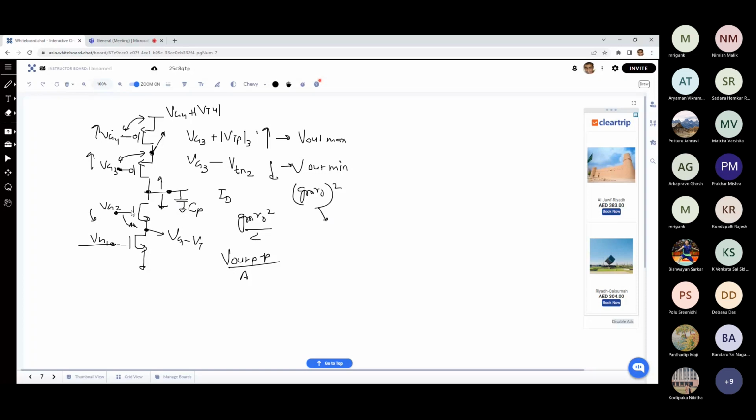So even if you say that output swing is somewhere close to, say, 500 millivolt, or 0.5 volt, the gm·ro squared is going to be much smaller, and therefore the allowed input swing is going to be much smaller. You can't apply a very large signal over here. It has to be very small, 0.5 millivolt, 0.25 millivolts, lower than 0.25 millivolts. So the input swing has to be small. This amplifier will be used only if your input signal is small, of the order of 1 millivolt or smaller.